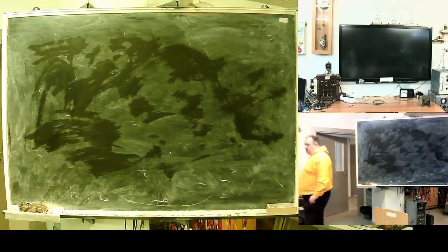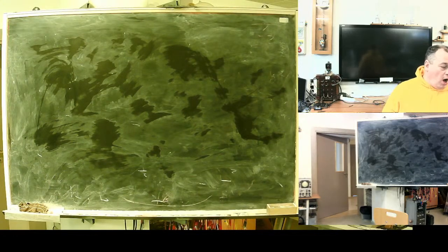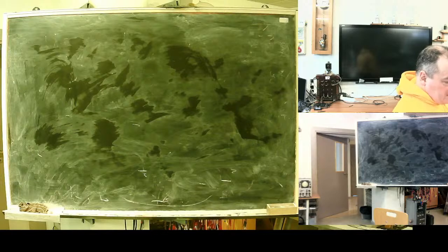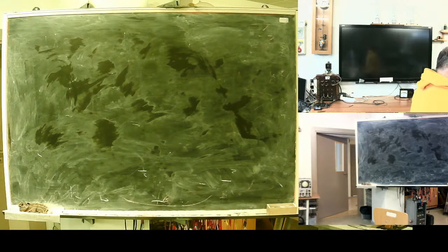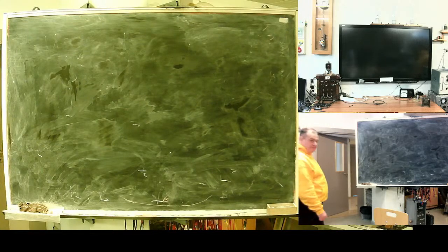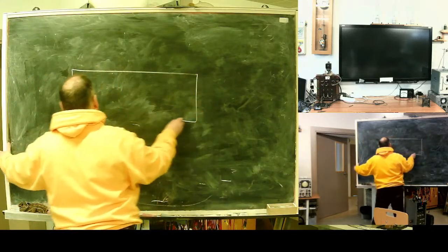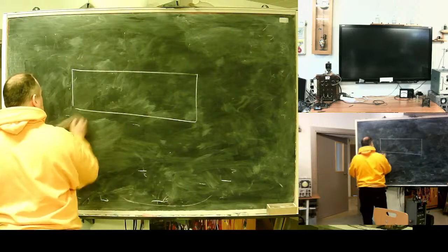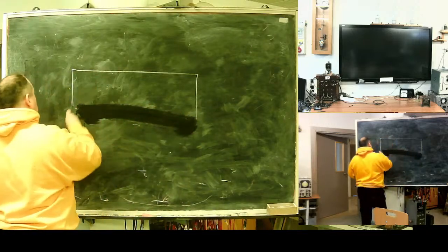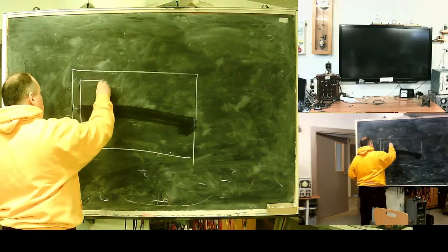Voltage networks can use a separate transformer for each phase or one transformer for all phases, but a special kind of transformer. Special. You cannot use an ordinary three-leg transformer as a current sensor. You need a special one, not every design is suitable here.